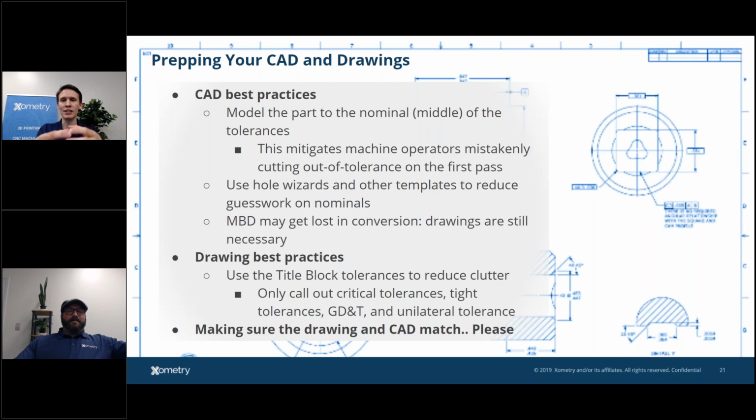The CAD is then used in their CAM software, so computer-aided manufacturing, interpreting what tools are required, how to actually process that part, the setups, the fixtures, it's all done virtually in this virtual machine to prevent any errors, and then it gets made in reality. If there is a deviation in your CAD from what you need, we're going to cut it that way. We're making it to your CAD. If your drawing is the wrong rev, and you give me a CAD model and you give me the wrong rev drawing, I'm making it to the CAD model.